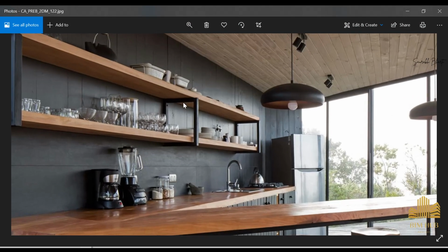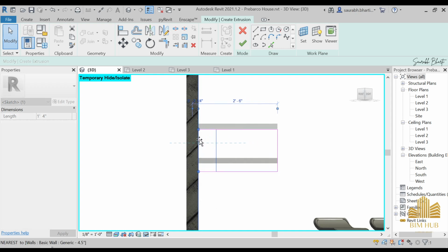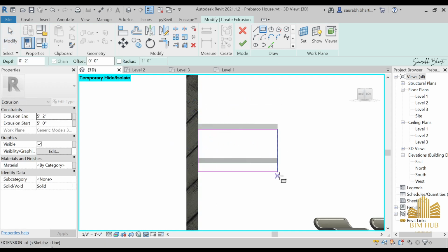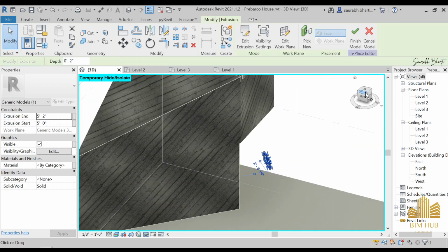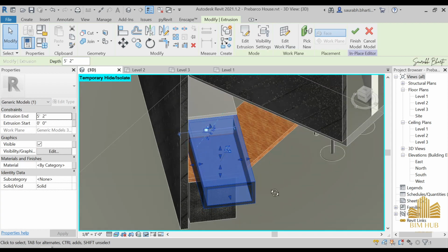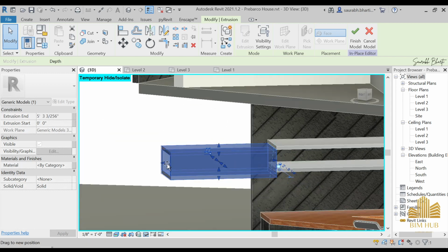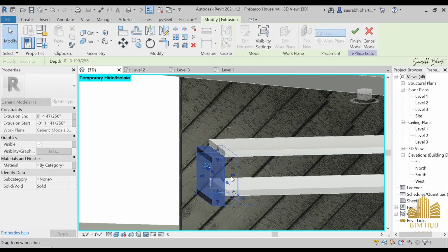This is of square type, and what we have made is a rectangle. Actually we have made something of rectangular type, so not a problem, let it be. So just go to this and here make an offset of 2 inches and then press spacebar, and now you will see that we have something like this at this point, and now we have created it, but we have to put it on the inside. So just follow this portion and then make it something like this,